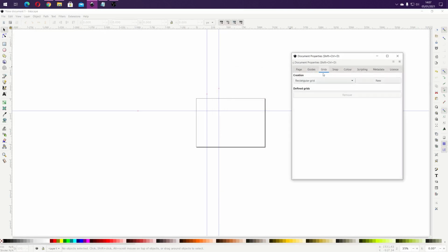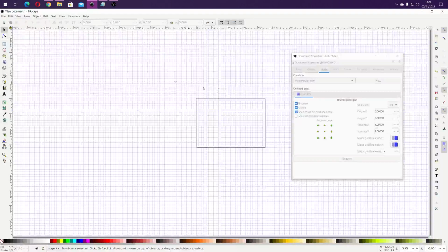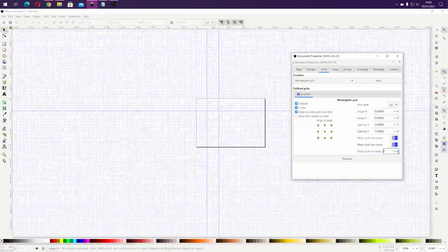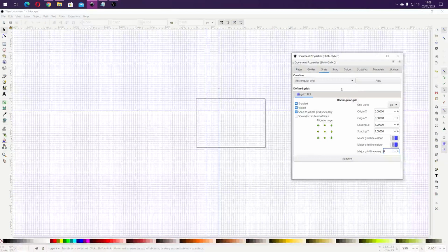And next thing is grids. To activate grids, you need to go to View and select the Page Grid option. After selecting that, you will see the grid on your area, which you can define the existing one and the density, increasing or decreasing, or you can prepare, for example, few grids in different units which you will be using later.